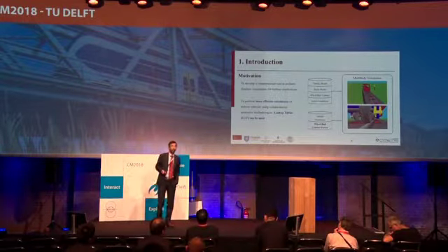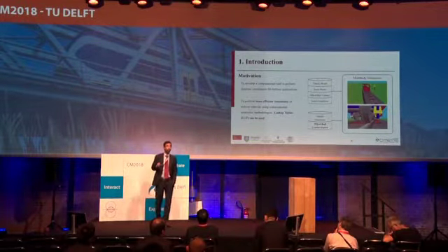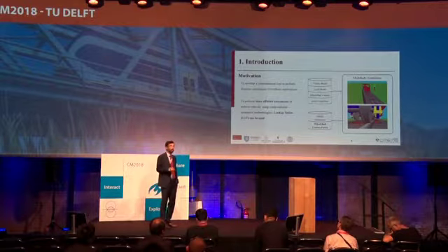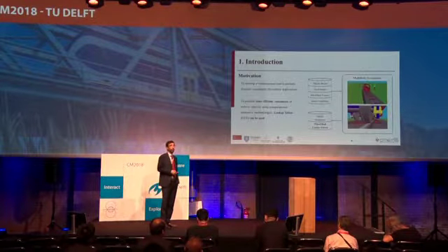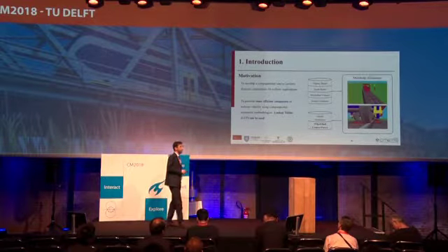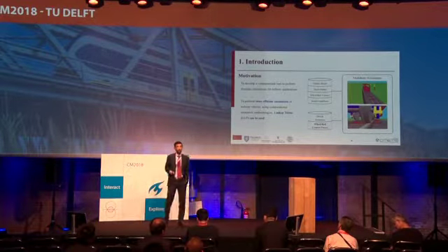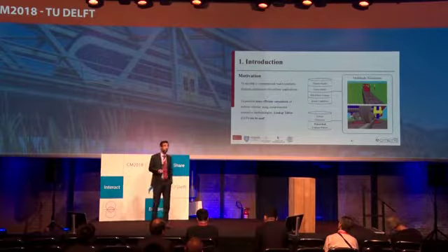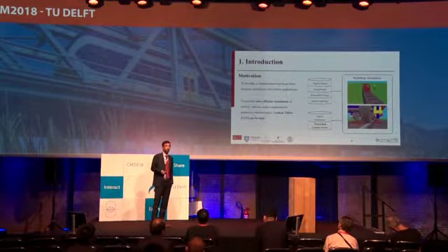Where is the problem? If you stick to elliptic contact patches, then this is quite simple. If you go into non-elliptic, you need to add additional dimensions in your contact table to consider the non-elliptical shape of the contact patch, which means the size of the contact table you're building becomes greater, and you may have problems with the time required to produce the contact table, and especially with the storage and interpolation of that table.